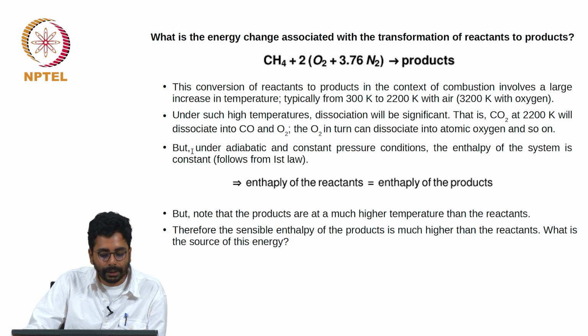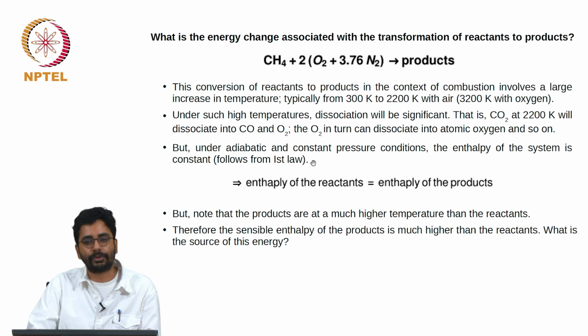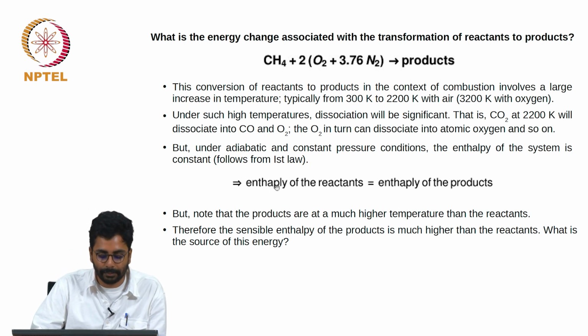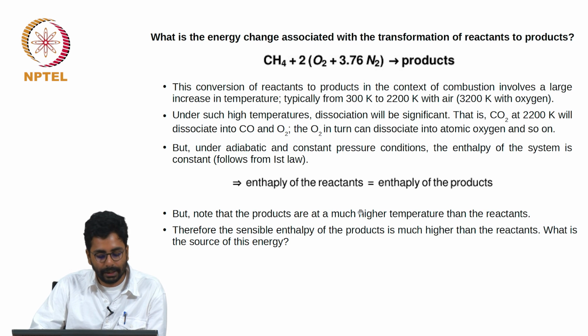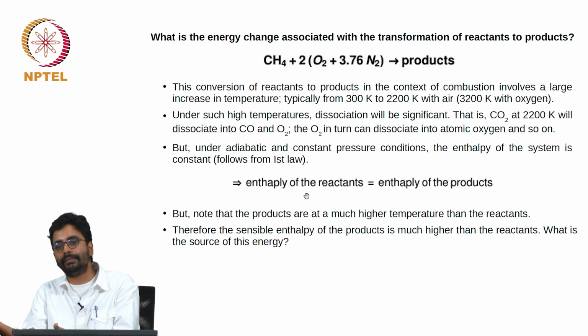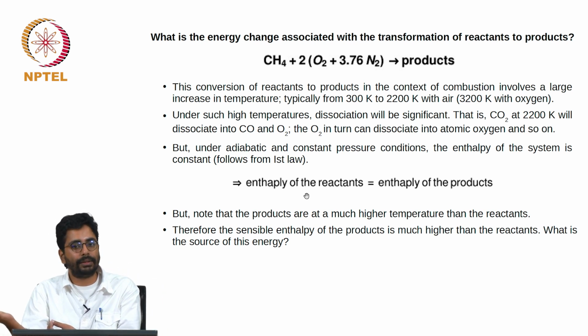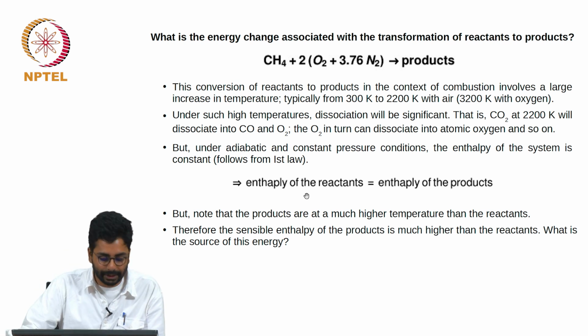Under adiabatic and constant pressure conditions, we know that the enthalpy of the system should be constant by application of the first law of thermodynamics. So the enthalpy of the reactants must be equal to the enthalpy of the products, but note that the products are at a much higher temperature than the reactants. Therefore, the products have a very large sensible enthalpy and the reactants do not.